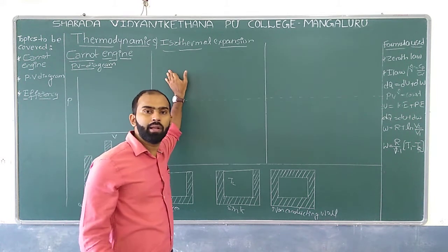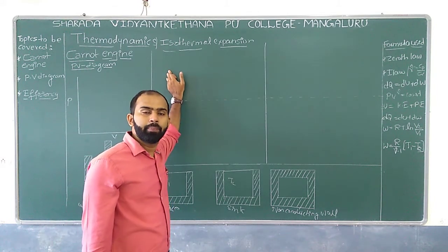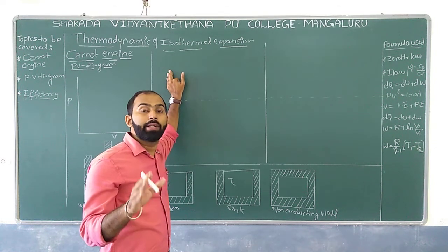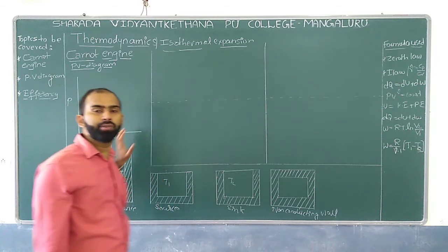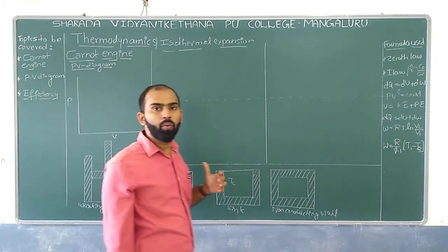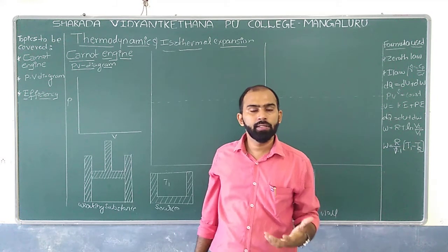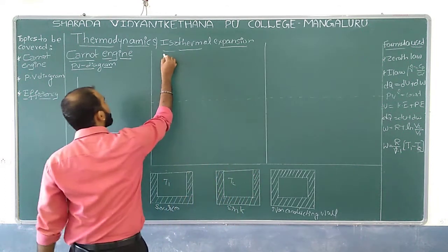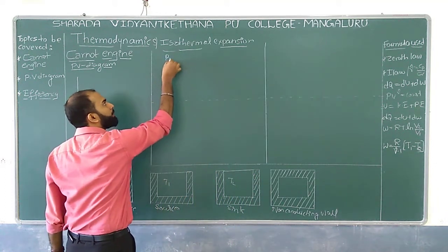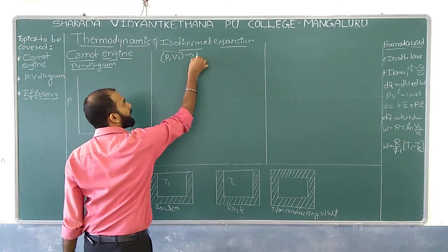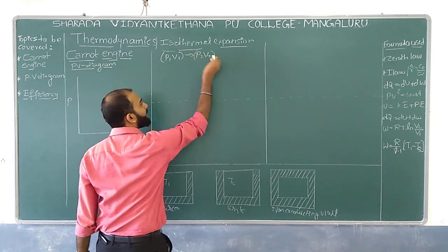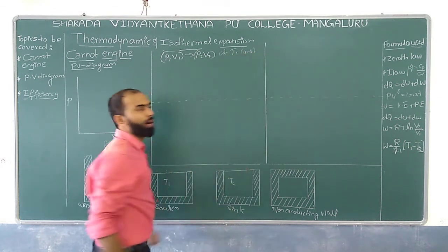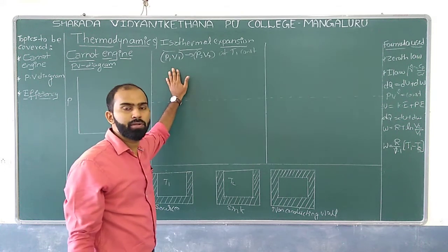Well, so what happens in isothermal expansion? Since it is isothermal, what parameter remains constant? What do you mean by isothermal process, by the way? It's a process in which temperature remains constant. To maintain a constant temperature, the parameters that are varying over here are pressure as well as volume. Which means the initial pressure is maintained, P1 V1 to P2 V2, at T1 as a constant. So this is what exactly we can expect under isothermal expansion.